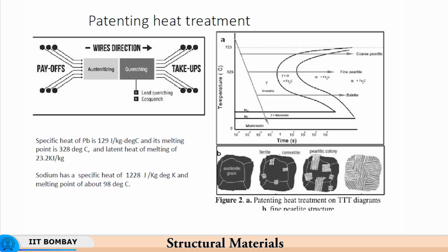You have to be conscious of the fact that you have overloaded the ropes, and you have to be careful next time you lift using this overloaded rope, because by overloading it you could well have gone beyond the yield point of the material, and then you might have resulted in some plastic deformation. So, if that has happened, it is better to not continue with it, because you do not want it to keep on elongating with progressive overloads.